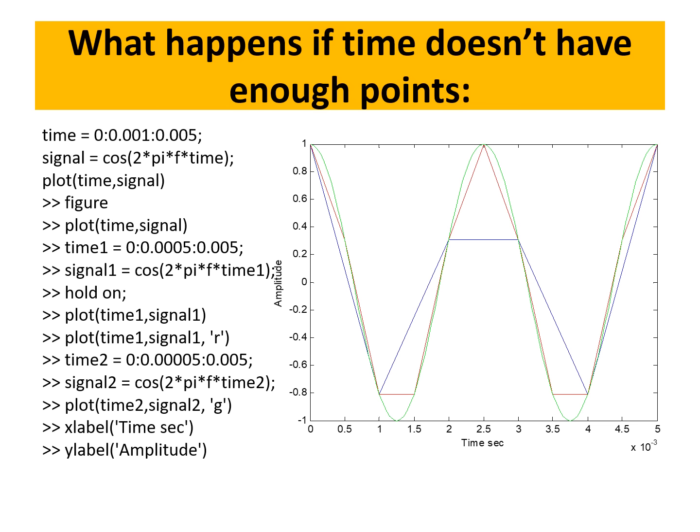Over the sampling problem that we did before, let's go and write this code in MATLAB, and you don't have to put the greater signs in your file. Just create a new file and put all of these. So if you recall, what is the Nyquist threshold? It has to be twice the largest frequency in order to have a signal that you can reconstruct without losing information.